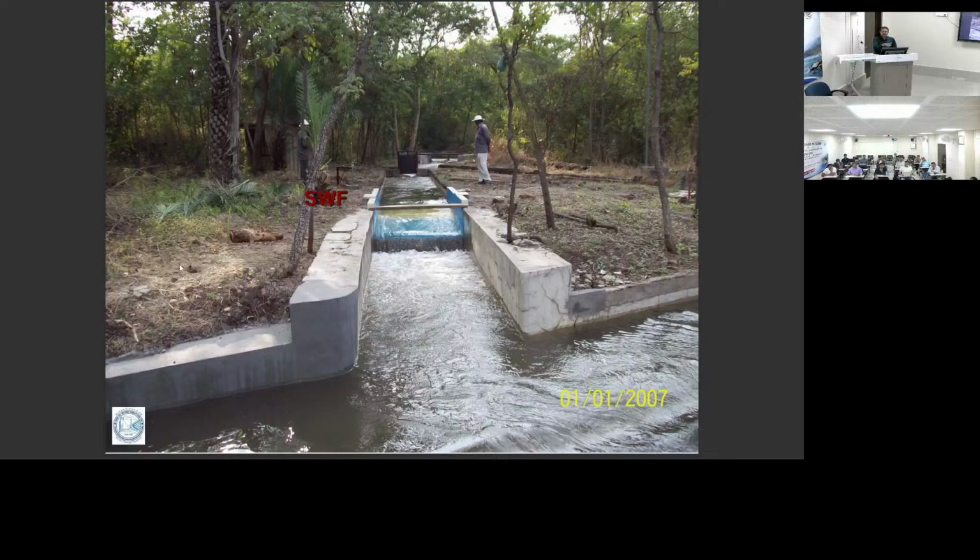For V-notch you can also measure, but V-notch will give a lesser discharge, and with the Rehbock weir you get the accurate discharge. The only thing is that for the Rehbock weir you have to make a hole on the downstream to remove the negative pressure created under the nappe. That is the main thing. But here it is not like that. But the accuracy is more in the Rehbock weir or thin plate weir compared to the standing one.